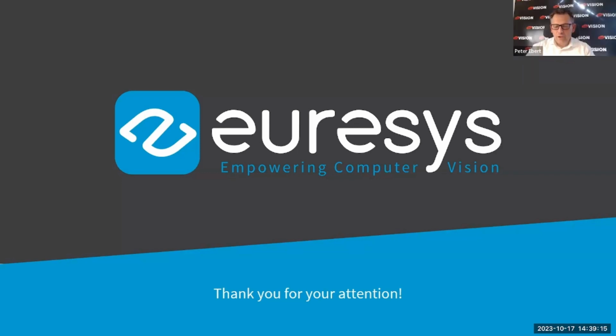And is the delay tool able to manage several events at the same time? Yeah, it's possible. Actually, the delay tool operates like a delay line. So it may accept a new event while the previous one has not been delivered yet. So it means that the delay tool is able to record a sequence of up to 16 different events. And actually, on the frame grabber, there are 2 delay tools. So you can choose which one you want to use.